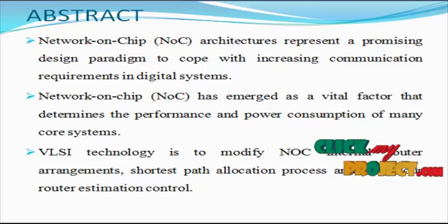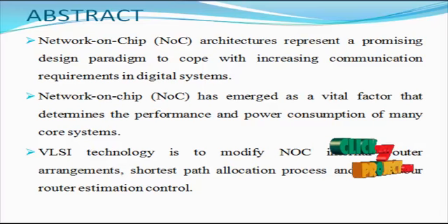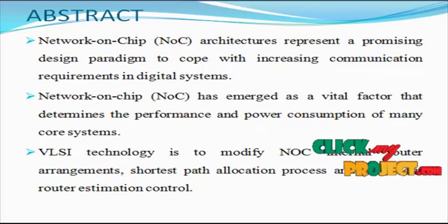Due to 3D NoC manufacturing technology limits and design complexity constraints, current 3D NoC research focuses on simple 3D mesh topology. Ideal analysis shows that the 3D mesh XY is a deadlock-free algorithm that achieves better system performance under a middle size of interconnect and typical traffic pattern. But in a larger system with increasing cores and various specific applications, the traditional 3D mesh framework leads to extra delay and reduced performance.